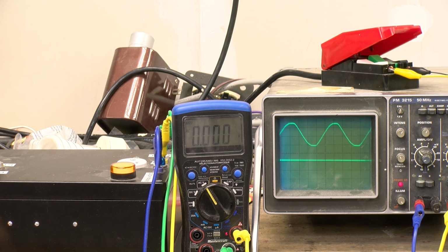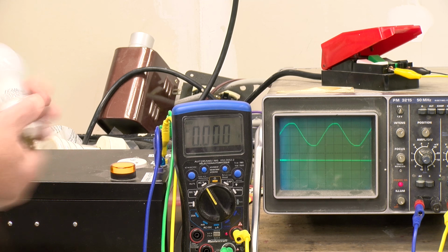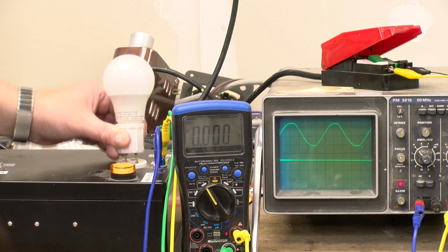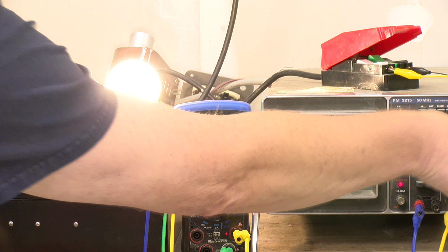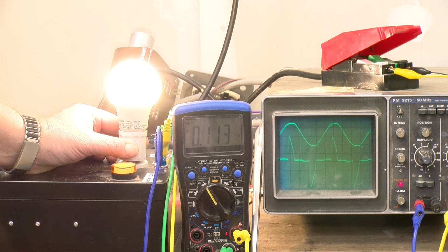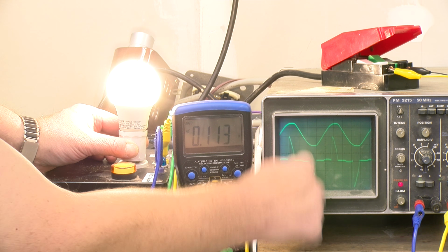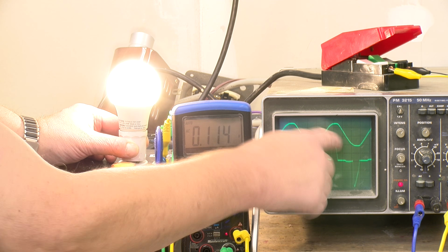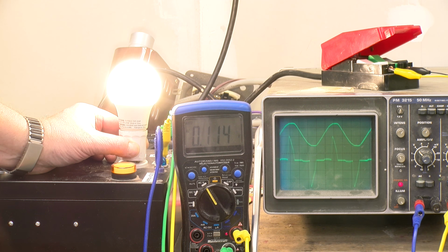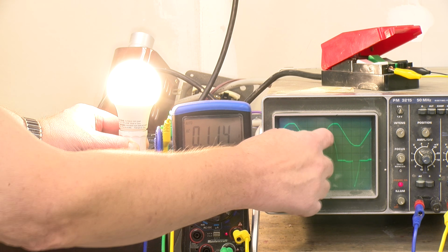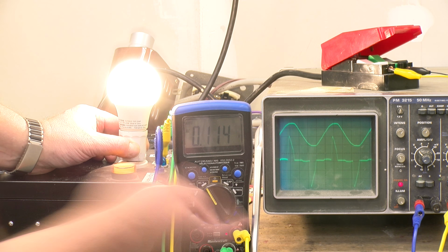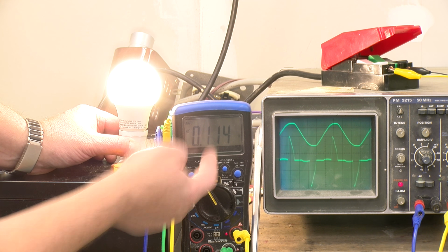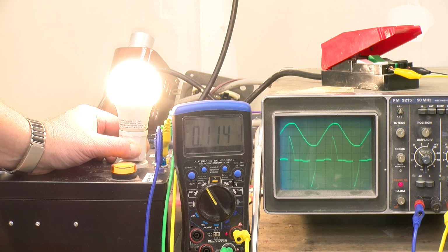I have a selection of bulbs that I just pulled from various places in the house. That's quite typical. This is a Noma bulb, and you can see, like we'd seen before, a very classic charging of a capacitor in a very simple electronic power supply producing really large spikes. And the real problem is even though this bulb in theory is only consuming about 1/10 of an amp or so, these spikes are really high.